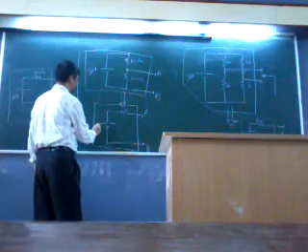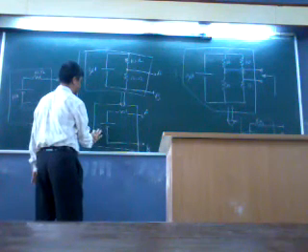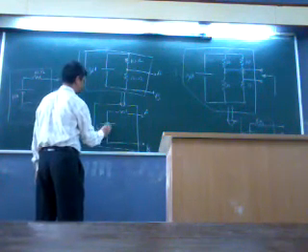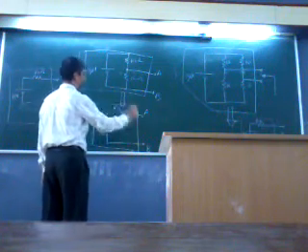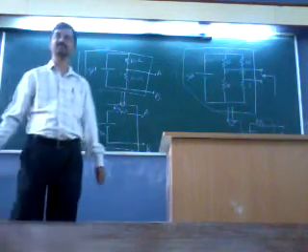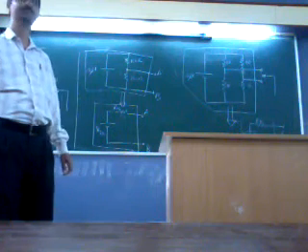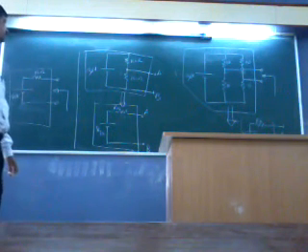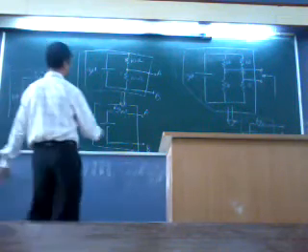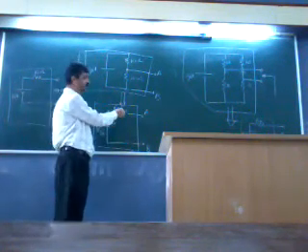This is VTH, this is RTH. What do you find out? 30 volt and 20 ohm. Answer is 30 volt and 20 ohm. This is 30 volt. Yes. This is 20 ohm. Yes.